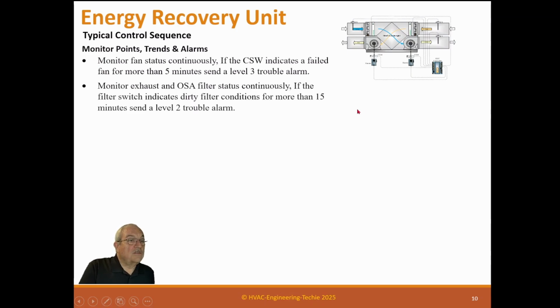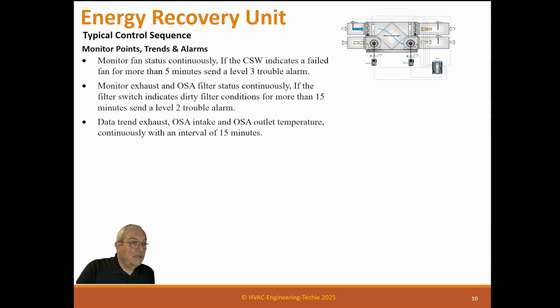Monitor exhaust and outside air filter status continuously. If the filter switch indicates dirty filter conditions for more than 15 minutes, send the level 2 trouble alarm. Data trend exhaust, outside air intake, and outside air outlet temperatures continuously with an interval of 15 minutes.